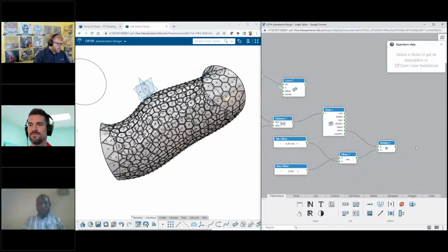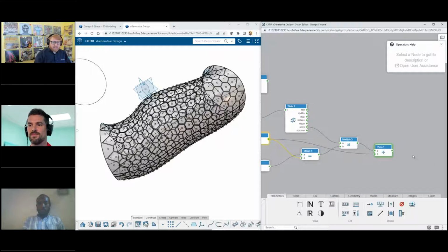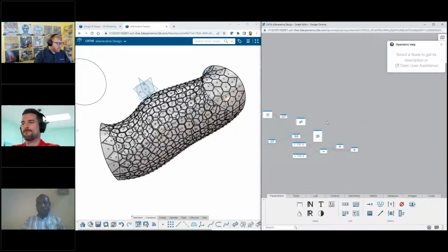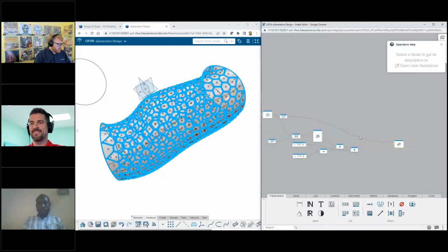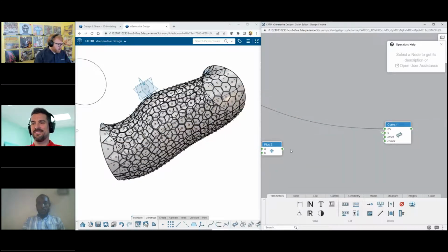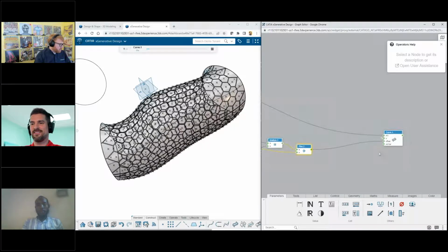And then if I add, so I say plus the min value, now the highest number that I'll see in here is 2 millimeters, and the lowest number that I'll see in here is 0.25 millimeters. And then I've got all that figured out. So now I can plug that into my offset distance, and it will be specific to each face.